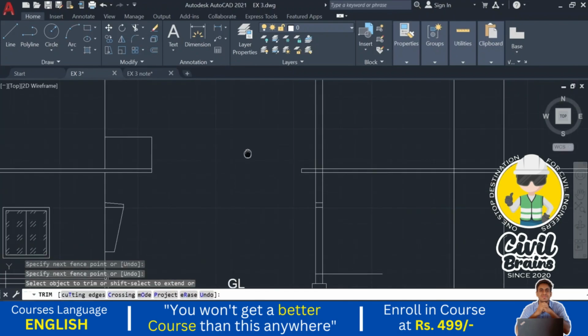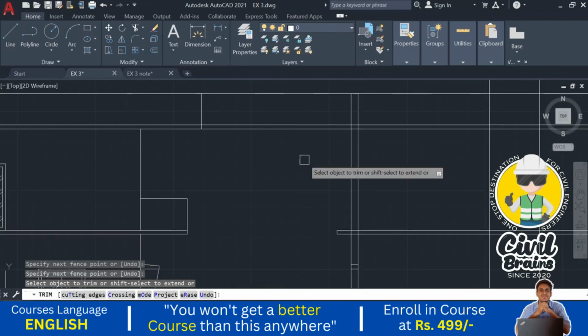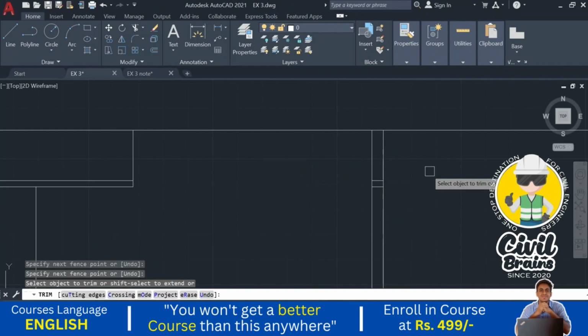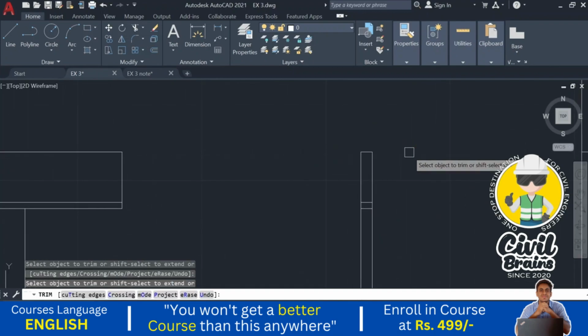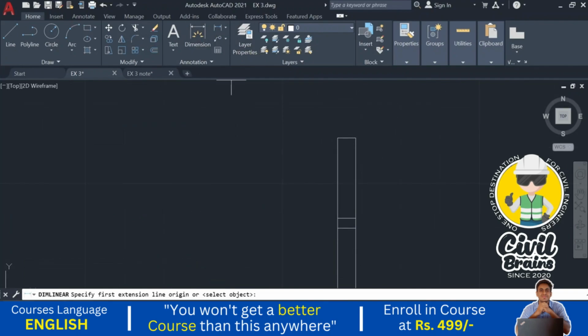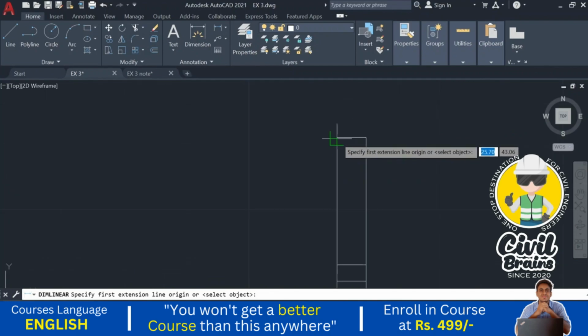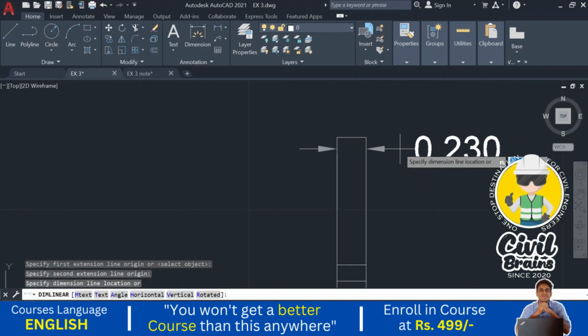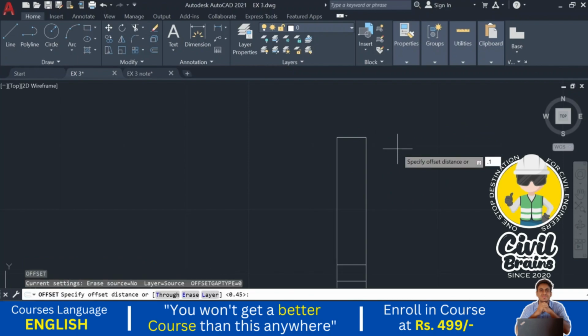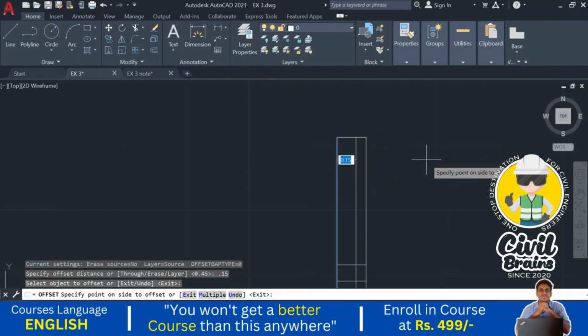Okay. Next, here we come again. Here we have not shown the lintel. I just tell you, that is a parapet, correct? So here we have not taken the width of the parapet as 0.23 meter. We have taken the parapet width as 0.15 meter. Offset 0.15 meter, the width of the parapet we have considered here.